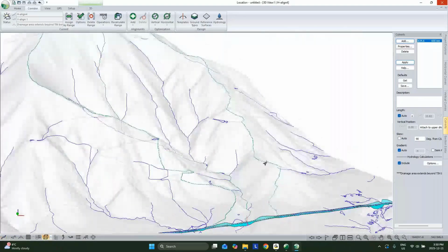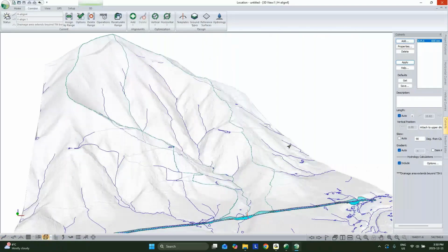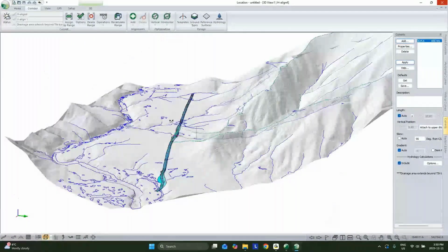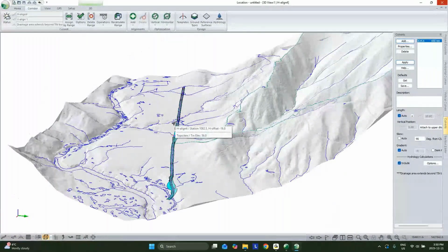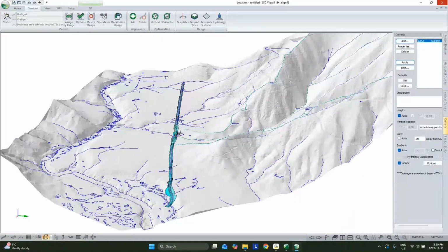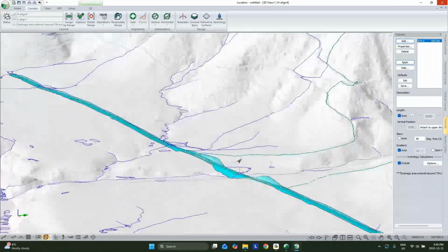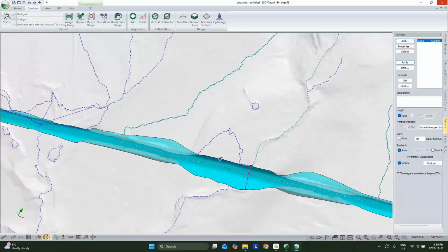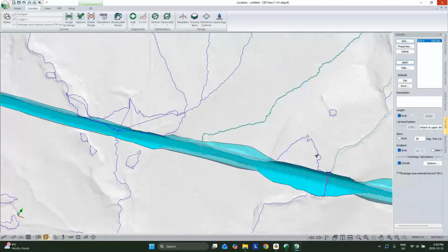We could populate the summary in our data table for what's the drainage area to each culvert. And then if it's kind of like what we have here, an intermediate step where we haven't added our culverts yet, well, we've added that one. We can see that we've got some water backwatering back here. Maybe we add in another pipe, or maybe we add in an independent ditch to deal with that ponding area.